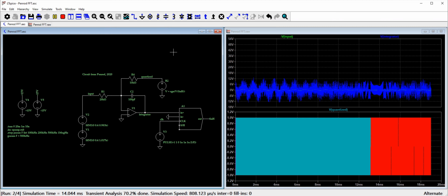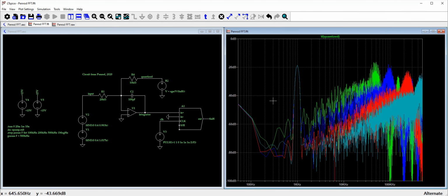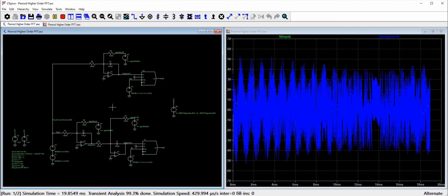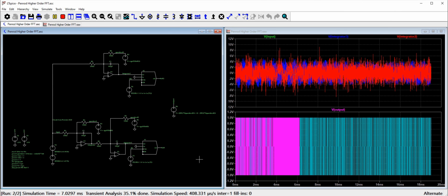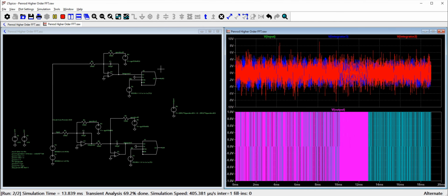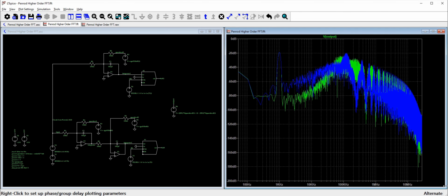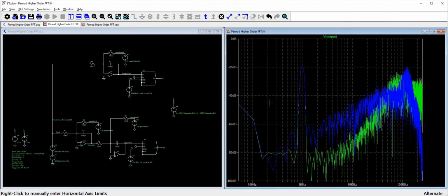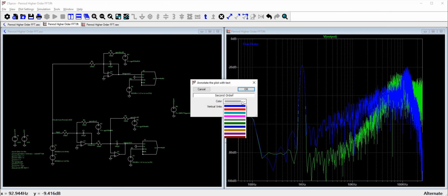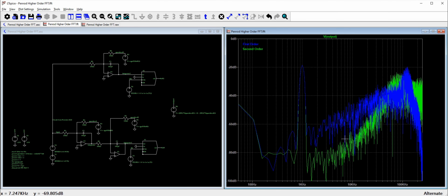Oversampling comes into play. For a fixed input frequency limit, the higher the modulation frequency, the lower the quantization noise at that frequency, up until the physical noise floor is reached. Just like a regular filter, multiple integrator stages can be cascaded to achieve a higher-order response, increasing the high-pass slope by 20 dB for each stage added. This way, a third or even fourth order response can be achieved. The advantage here is that a smaller oversampling frequency is needed to achieve higher SQNR at a given frequency.